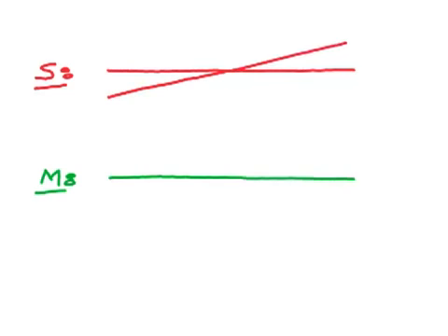Now we know that the shear force will vary linearly, and if you look carefully, we know that the shear force has a value of WL upon 2 minus Wx. If x is 0, in other words at the left side of the beam, the shear force will act down with a value of WL upon 2. That means it's a negative shear force of value WL upon 2. And if x is L, then the shear force will act up on the right-hand side, and therefore we'll have a value of WL upon 2 at the right-hand end of the beam.